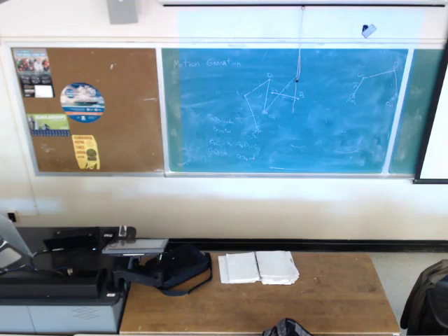as B1. Pick the corresponding point here by drawing a circle with this center and this radius. So I will find P2. Connect these two, extend them, pick a point here, and label that as O6. O6 is the location where I'm going to put the motor. Draw a circle with this center and this diameter.